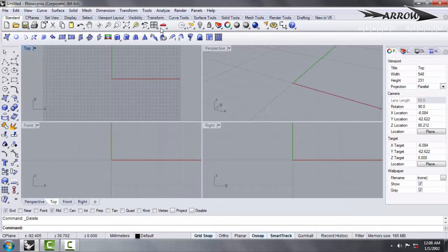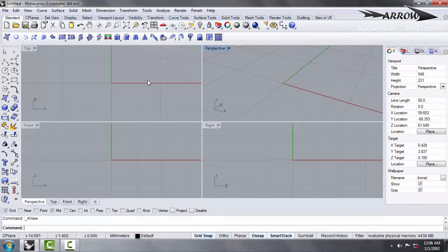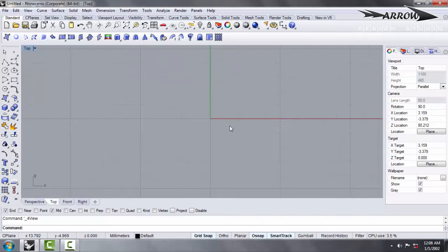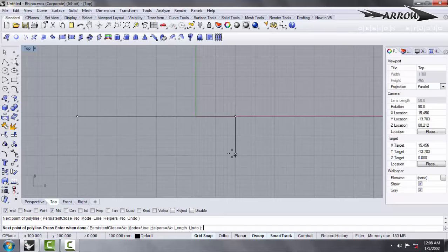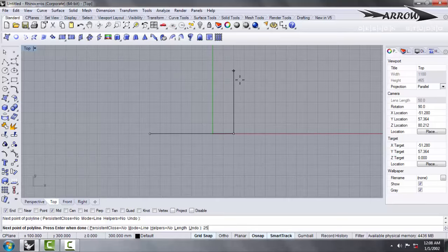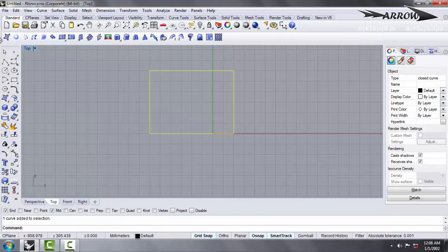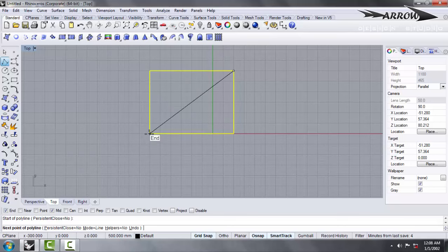Now this is my Rhinoceros 5.01. Now you can see everything over here. I can just say top view, I can come down into the top view. What I currently need to do is draft the longitudinal and latitudinal sides of this stool. I'll consider it as 400 horizontally this way, and I'll take 250 this way. It is tentative, so I can say 300 as well. This again is 400, and I have drafted a rectangle of 400 by 300 over here.